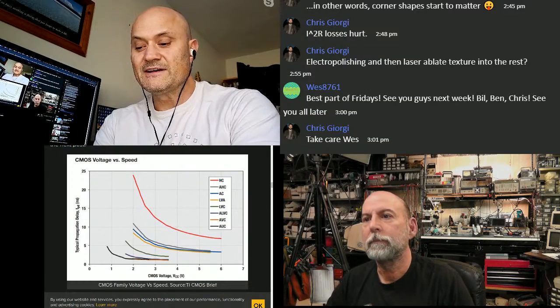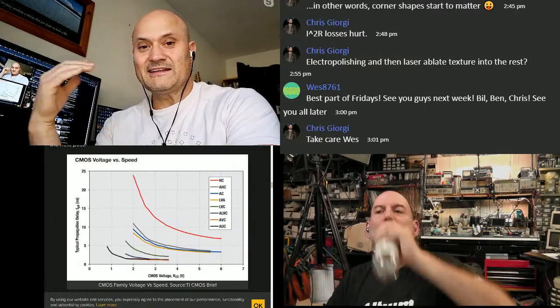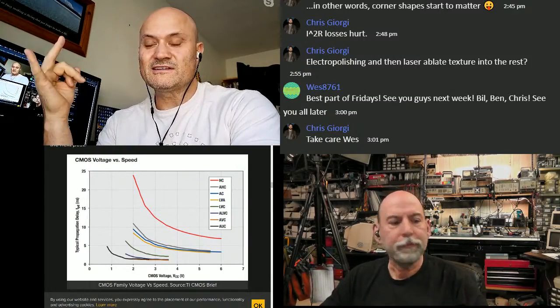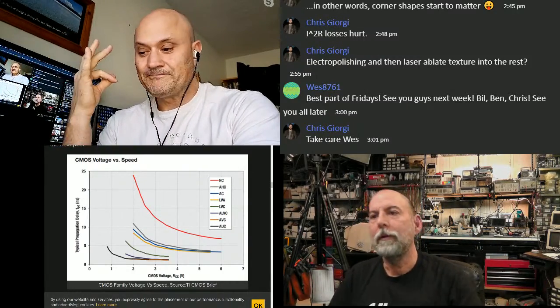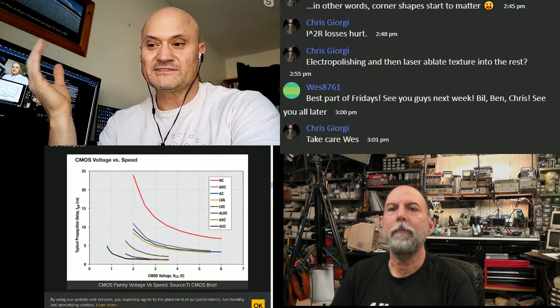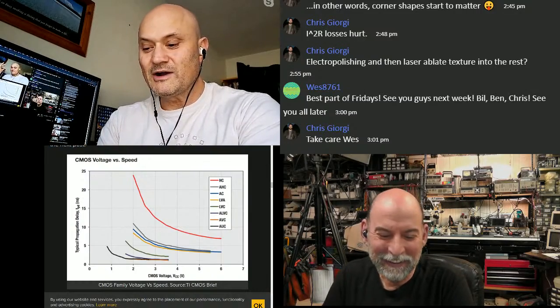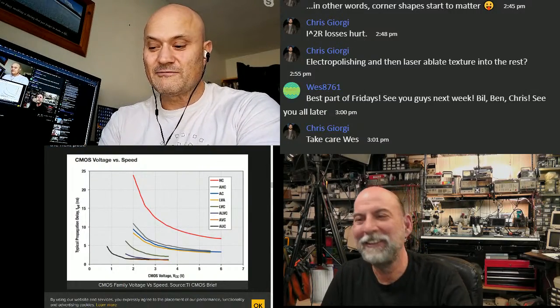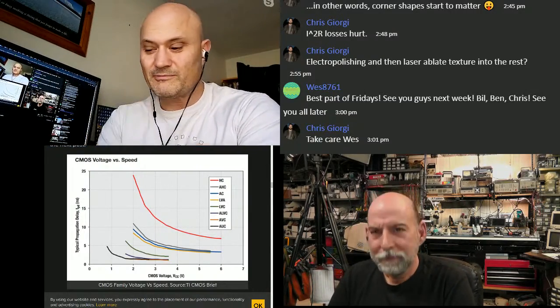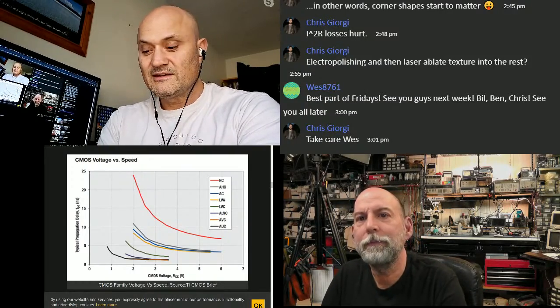And some of them will say, well, we have our standard processes for 4 and 6 and 8 layer boards, and they have test coupons for those, which they just keep around. And if someone asks for a coupon, they send them one. Send them one, and it may not necessarily come from the panel from your production run. So if you want that, you've got to make sure you ask for it.